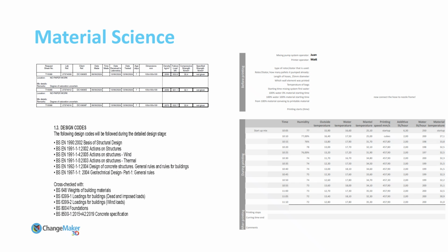which have been undertaken in a traditional manner in the UK by pouring 3D concrete printed material into a cube box container that was then tested and crushed by companies such as Socotec. You can see there that the crush data is in alignment with and supports that particular material data set. You can also see an example of some of the design codes that are used within the design principles and the design planning stage.